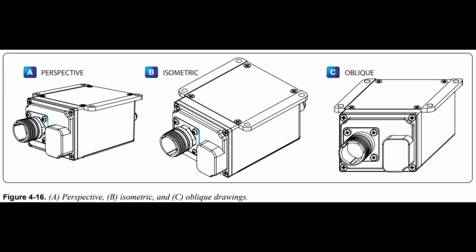Oblique drawings. An oblique view is like an isometric view, except for one distinct difference. In an oblique drawing, two of the three drawing axes are always at right angles to each other. Figure 4.16c.